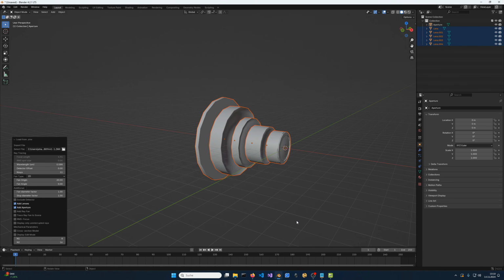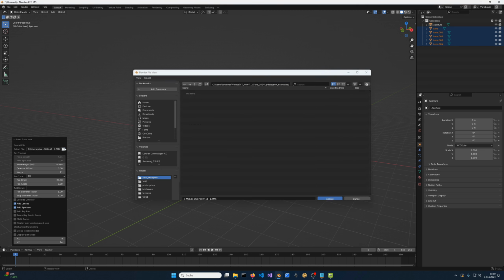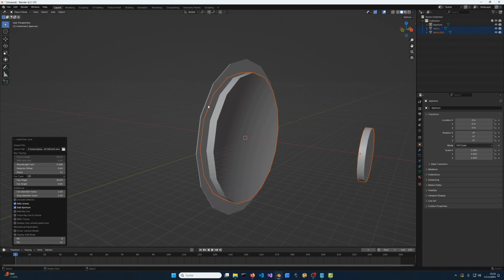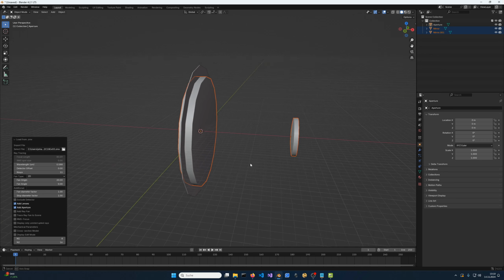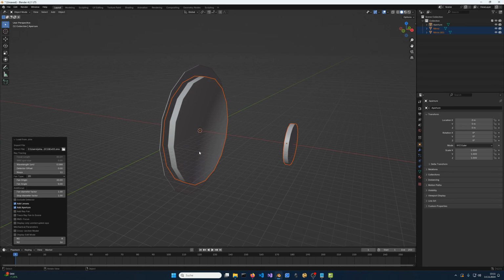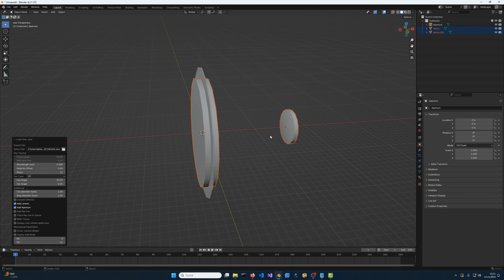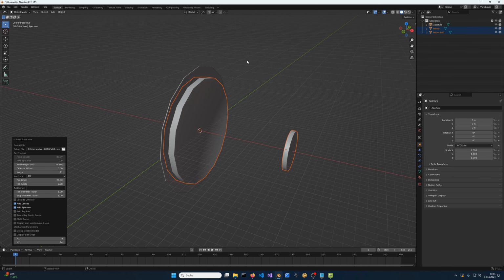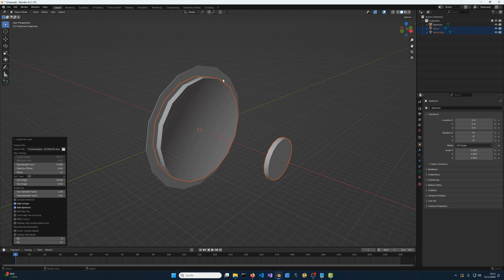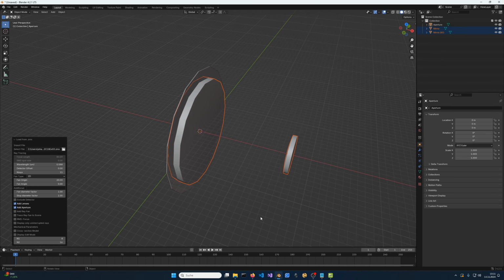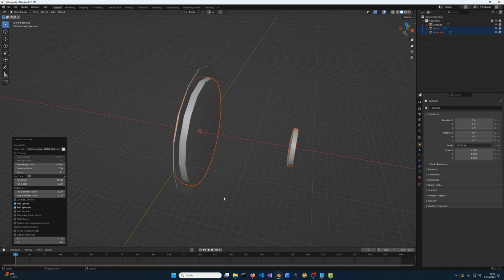And now for a last example of a working system, I want to again show a very different type of optical system, and that is that of a reflective telescope. It is just slightly larger than the mobile lens, this specific zmx file, because it's a scaled down system. What you can see here is two mirrors, one primary concave mirror and a secondary convex mirror, and the aperture is defined at the location of the primary mirror, which is why in this view it is drawn to intersect the mirror, which is of course not really physically correct, but that's how optically the system is defined.